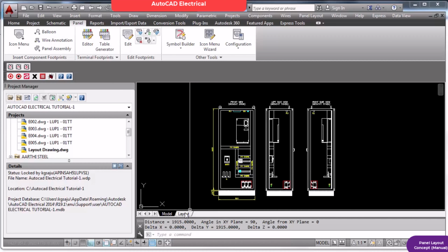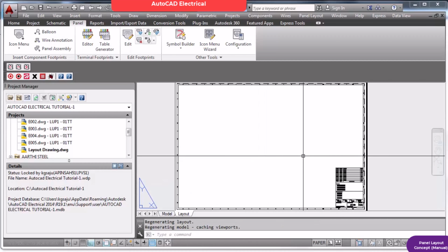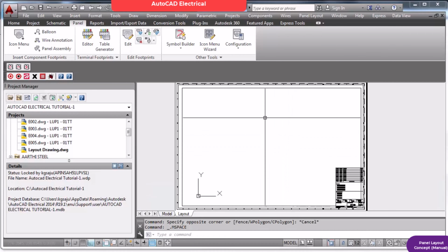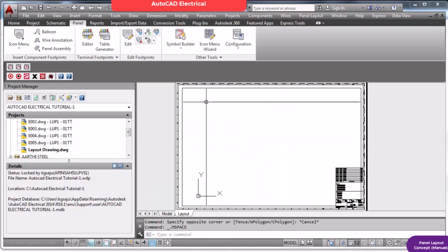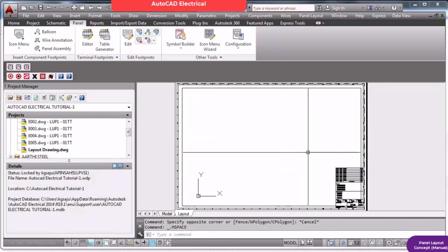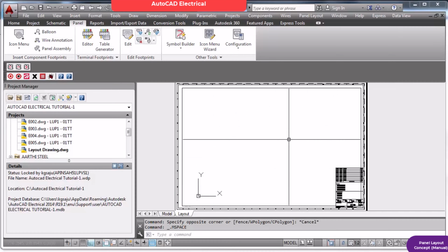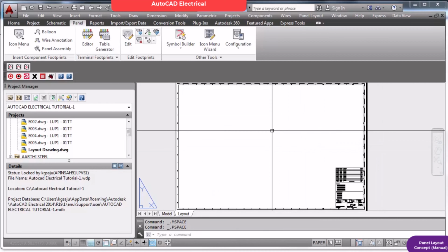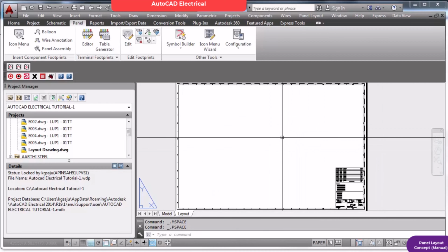The only way is you have to scale up your title block 10 times. Scale the title block and it will come automatically. But I don't want to disturb my title block. My title block should be of standard size. So if I move back to the layout, here this is now empty. If I double click here, now see my cursor moves inside. This is a viewport. Basically this is called a viewport. It is now moving here and there.